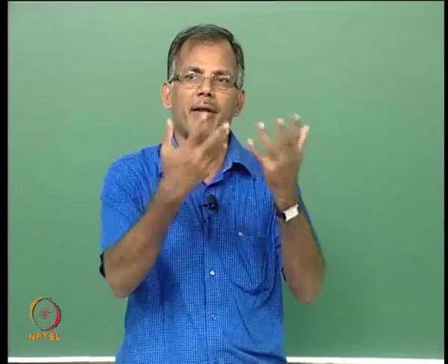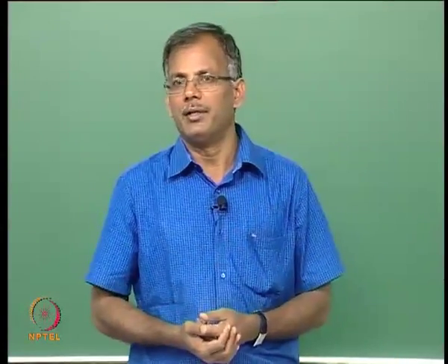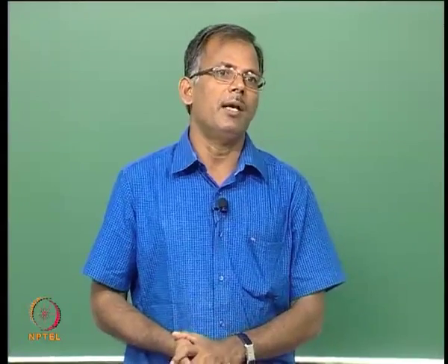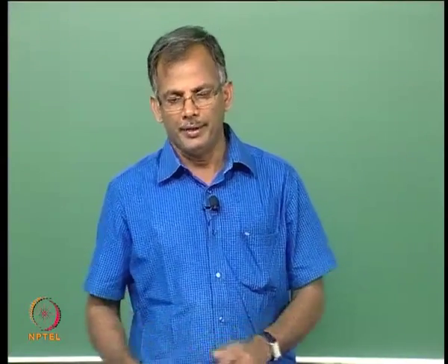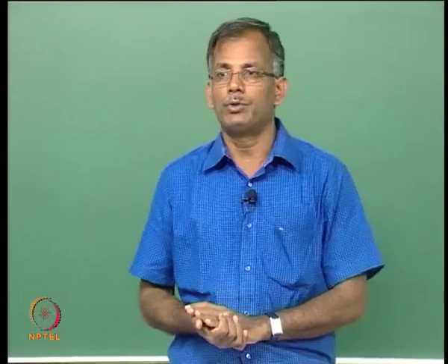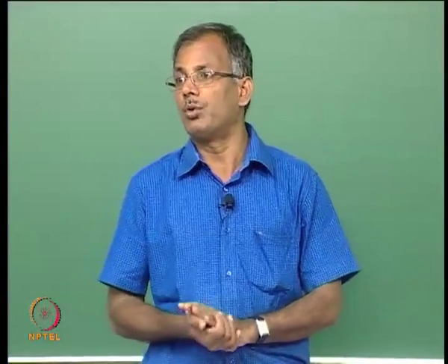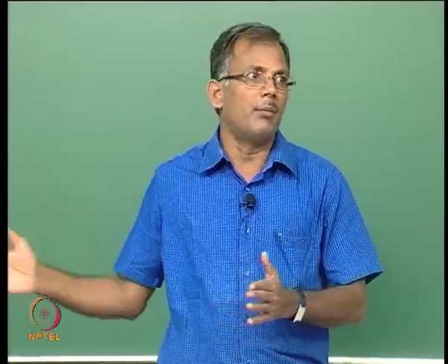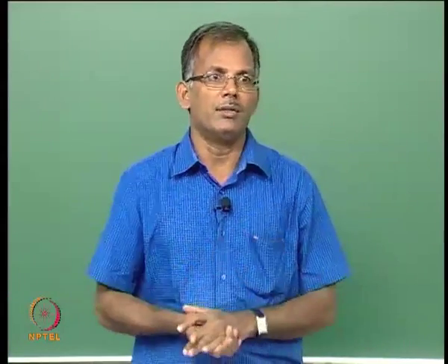If you have a breaking wave, the water particles get separated, so none of these theories will be able to apply. That is why you cannot calculate a wave force for a structure when the wave is just breaking or just broken. So, what we need is another idea. When the wave is breaking on a structure, at many of the port and harbor structures or coastal structures, many times waves come and break on the structure. So, how do we estimate?